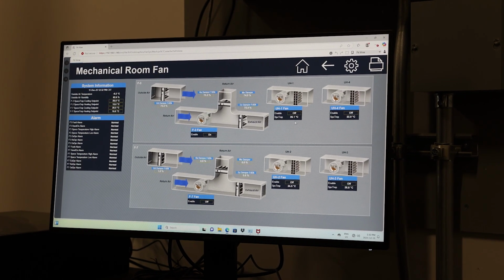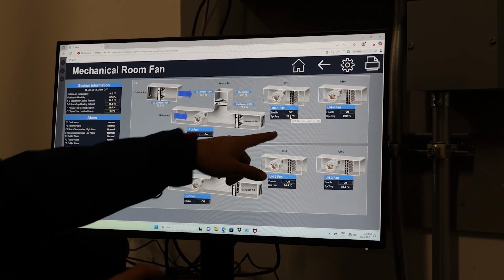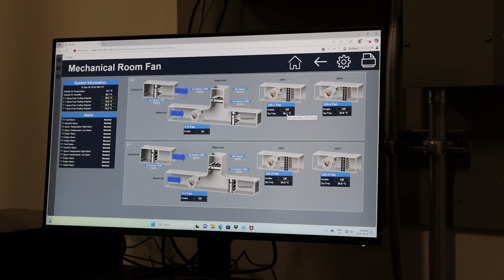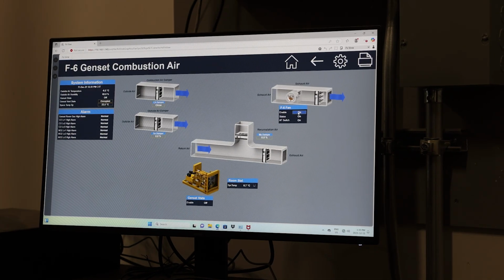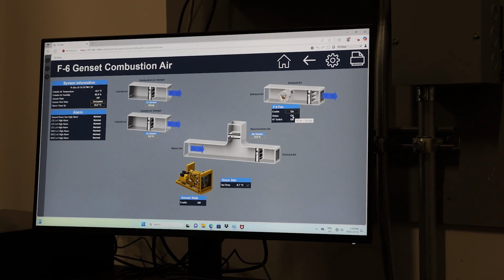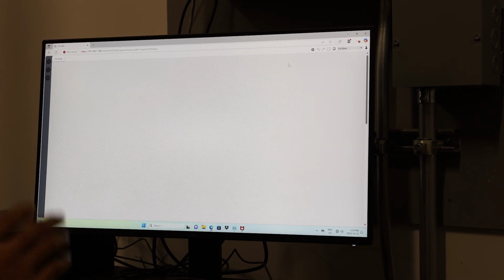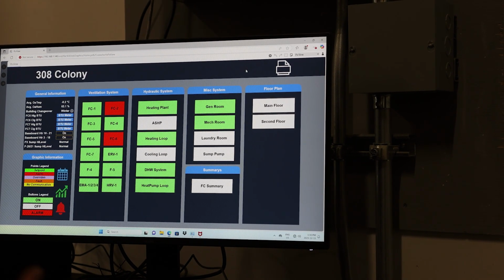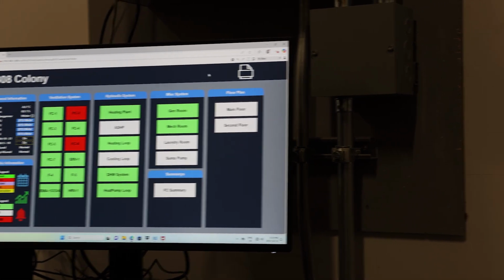For this system, if the fan failed, it will show orange. Or if the temperature failed, it will show 0, and it will be reading 0, and it will show orange. Oh, maybe they bind it to the command, not the status. So the BMS, for example, there are command and the status, just like this fan. We have enable, we also have the status, right? Status is the feedback that tells you the fan is actually running or it's not. So maybe in your scenario, they don't have the feedback. They only have a command. So the BMS is trying to run the fan, but BMS doesn't know if the fan is actually running or not. Maybe that's the case.